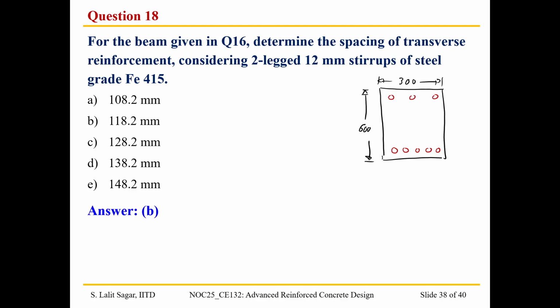This is going to be useful for us while designing the shear reinforcement. We need to provide 135-degree hooks.